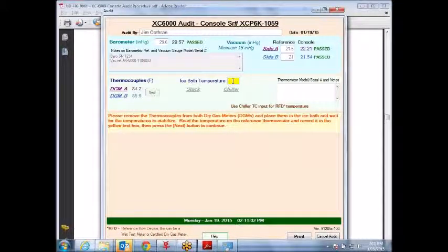Now what you have to do to get to the thermocouples on the portable consoles, if you've ever opened one up, is you open the door and you've got the two screws at the top. You loosen them and the front plate leans forward. Usually I put like a little box or something underneath it just so it doesn't lean over too far or fall off the bench, that type of thing.